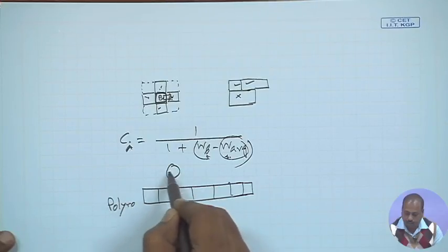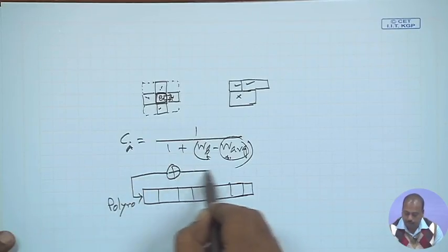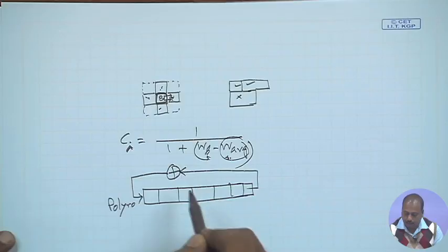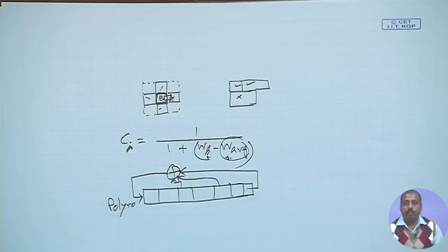There is an XOR gate, and this XOR gate feeds back the first cell, and what are the cell positions that you are tapping in? It may be that we tap out these two positions and take them into this LFSR. That will tell us what is the characteristic polynomial. If the characteristic polynomial is changed, then it will behave differently, so it will generate a different set of patterns.